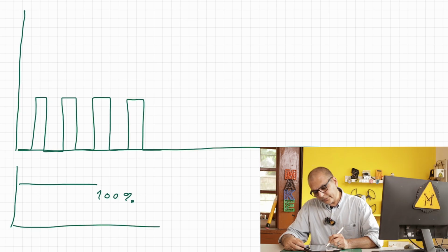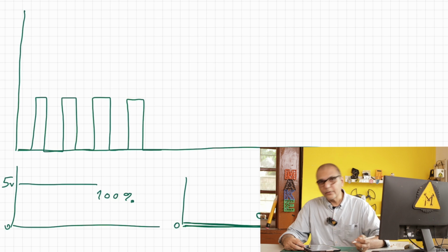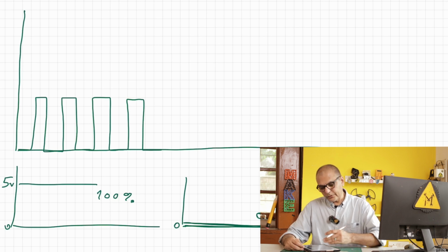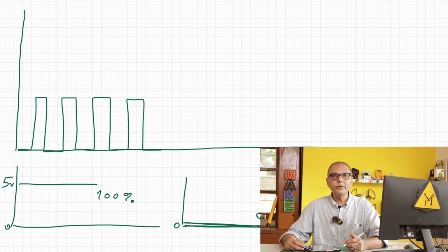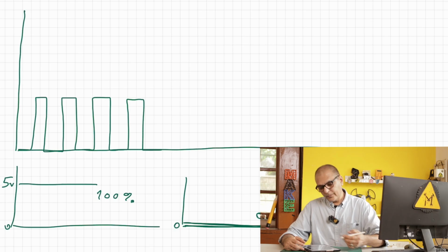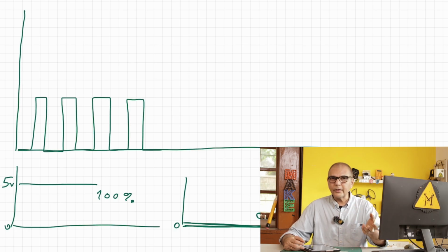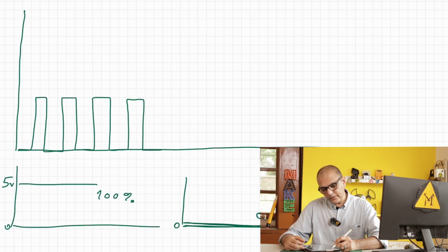On the other hand, if the same signal is at 0 volts, then that would be 0% output, obviously. Now, what if you want something between 0 and 100%? The easy thing is turn it on for half the time, turn it off for the other half, and that frequency can be anything we choose. That is a little bit irrelevant for the current discussion.